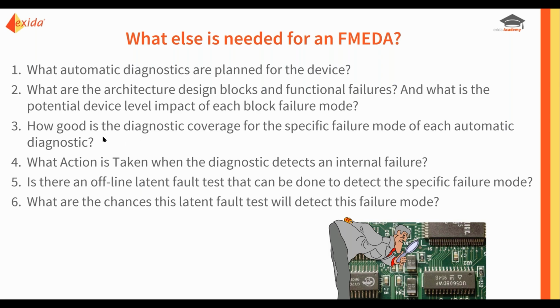Number 3, we need to know how good is the diagnostic for this particular failure mode of this particular block. A diagnostic may very well have different diagnostic coverage factors for different blocks and different failure modes. And we need to know what action is taken when a diagnostic detects an internal failure.